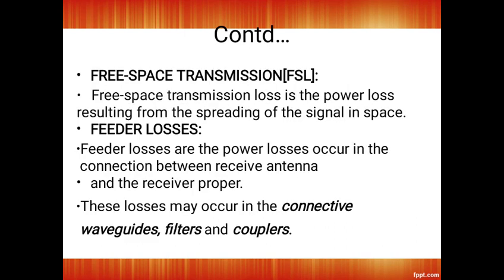Free space transmission loss is the power loss resulting from the spreading of the signal in space. Feeder loss is the power loss that occurs in the connection between the receive antenna and the receiver proper. These losses may occur in connecting waveguides, filters and couplers.